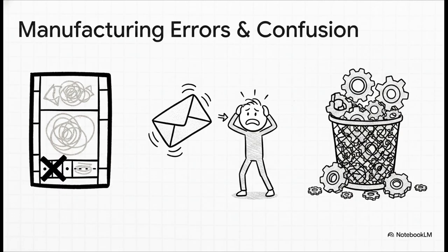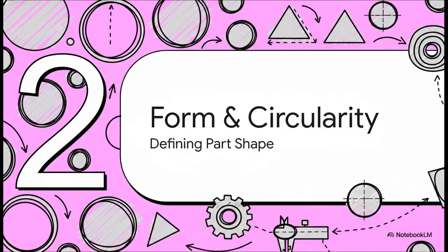And these aren't just harmless typos. Misordered modifiers or bad datum references will absolutely ruin your roundness controls and completely alter how the part is interpreted. That leads to a ton of vendor confusion, those endless back-and-forth email chains, and ultimately your parts ending up straight in the scrap bin.